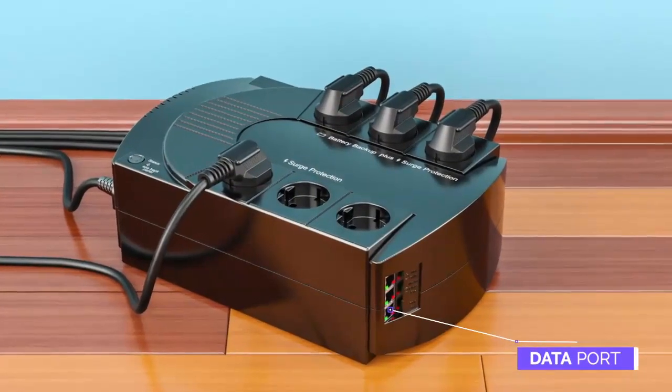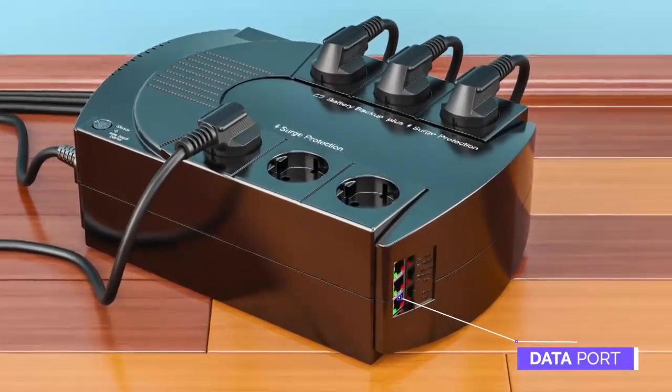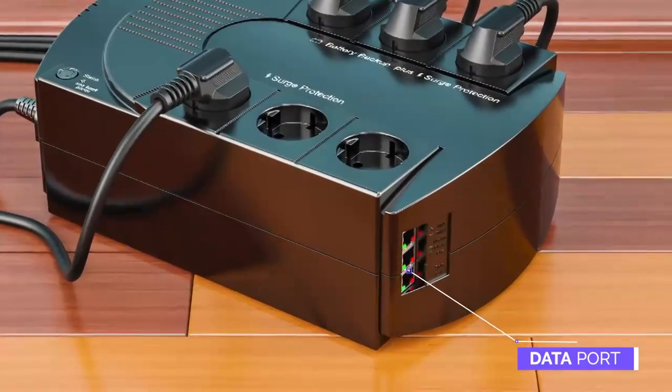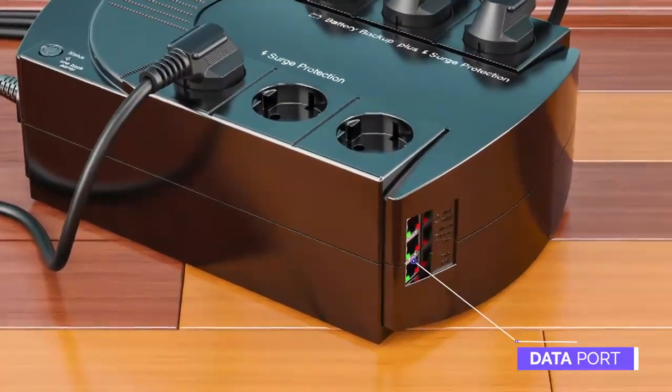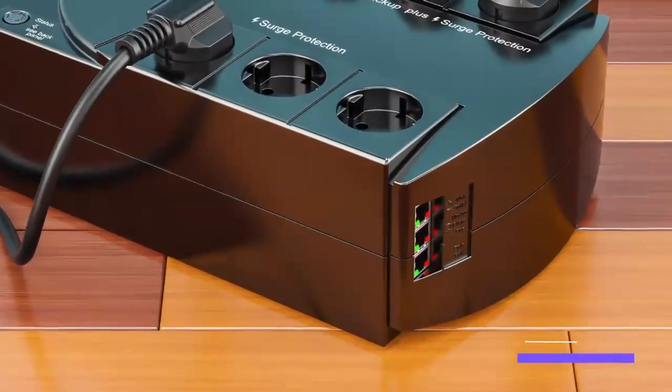Before we talk about how to configure a UPS, we need to bring up one key mistake that a lot of users make. People often plug their system's AC cable into a protected outlet on the UPS but they don't ever connect the management cable. Most UPS systems have a USB cable that you can plug into your PC system, which allows communications between the UPS and the computer's operating system. Using this cable, the operating system can monitor the battery's charge. In return, the UPS can send commands to the operating system to shut down.